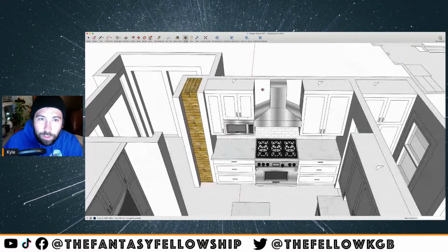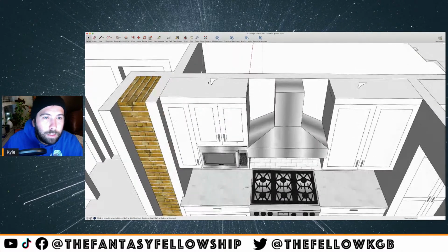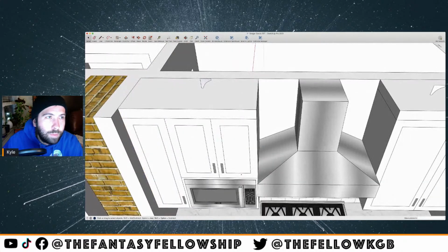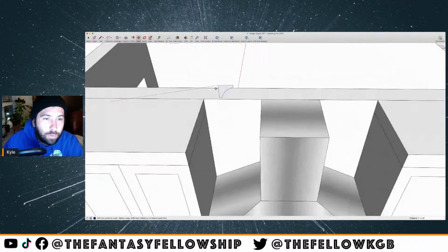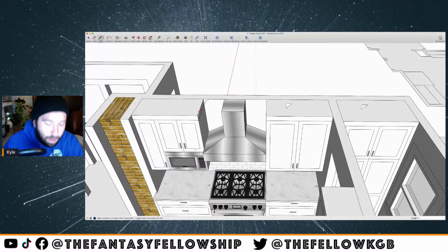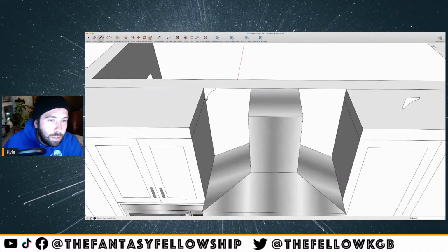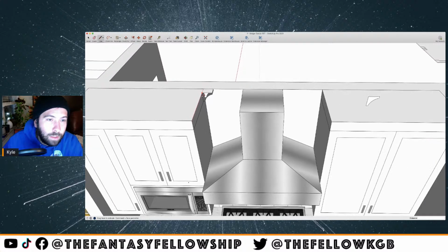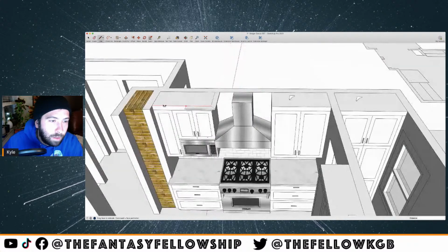So we'll come over to these uppers over here. I'm just going to take this crown piece. We'll start over here at this corner, and I'm going to make lines where I want my path for the Follow Me tool to go. So again, that's Tools, Follow Me. I'm going to click once. Oops, sometimes it likes to do that. Just don't be afraid to hit Escape. So click that once, and the red line it's following will be the crown molding. Let me go ahead and make that a group.